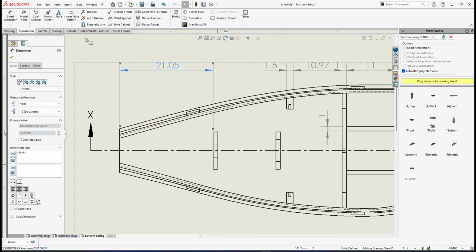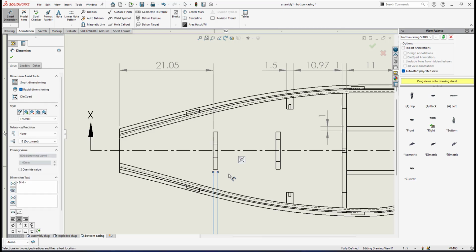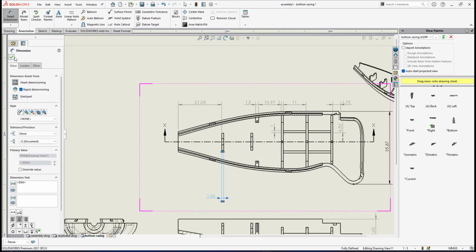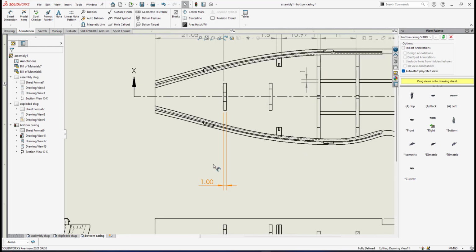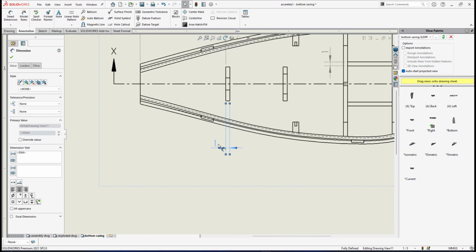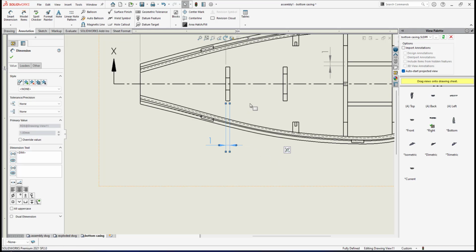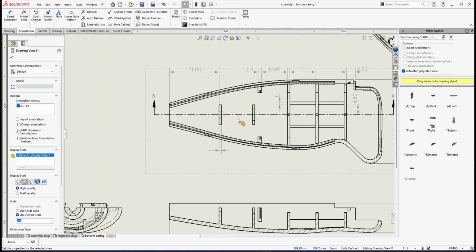So I have this, and also I can give the thickness of this grip. Or this one, I go for the bottom side. Click OK first. Then I can bring this dimension up until here. Make sure it's not too close, and not to the decimal point. Let me do some adjustment again somewhere here. So I already give the thickness of this rib to support the motor.